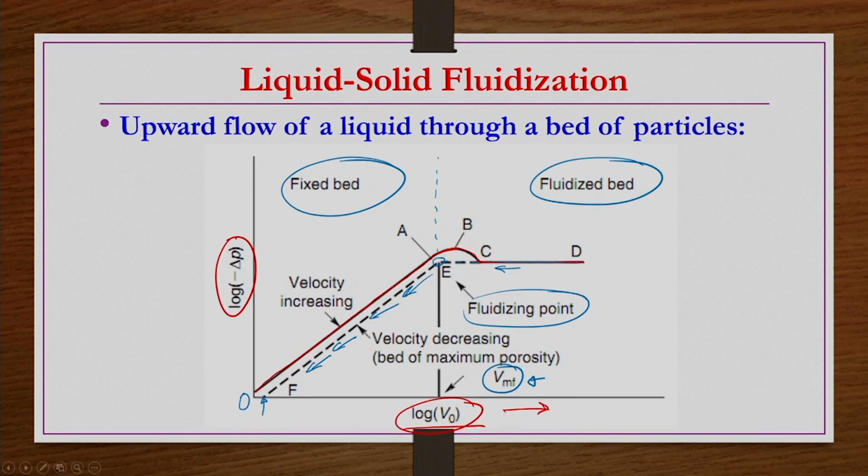That we can calculate if we know the minimum fluidization velocity. So, how to find out this minimum fluidization velocity is what we are going to see, and we are also going to see how to find out the friction factors etc. for these minimum fluidized conditions.